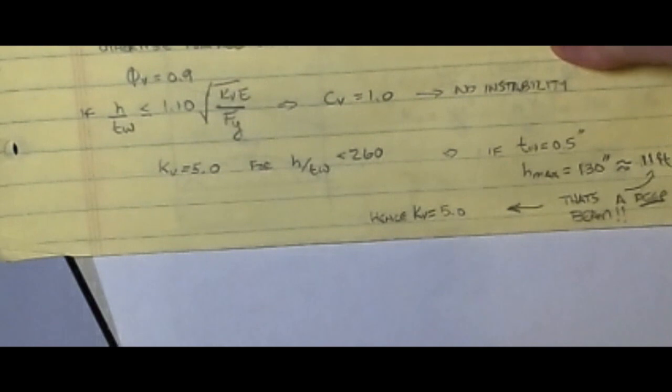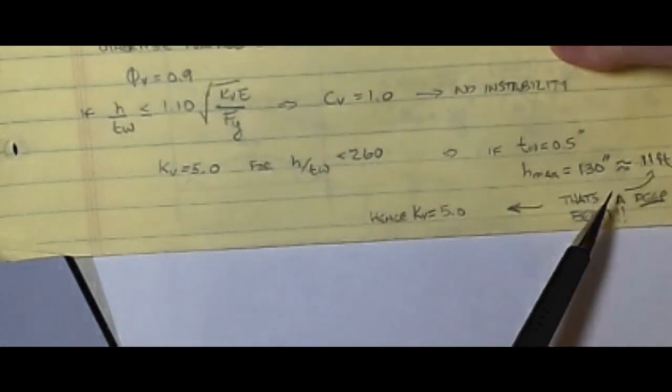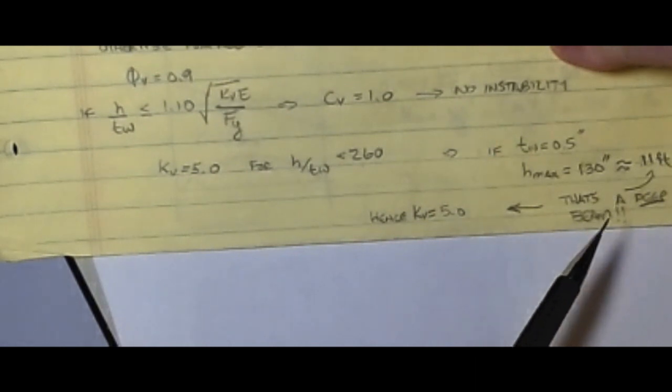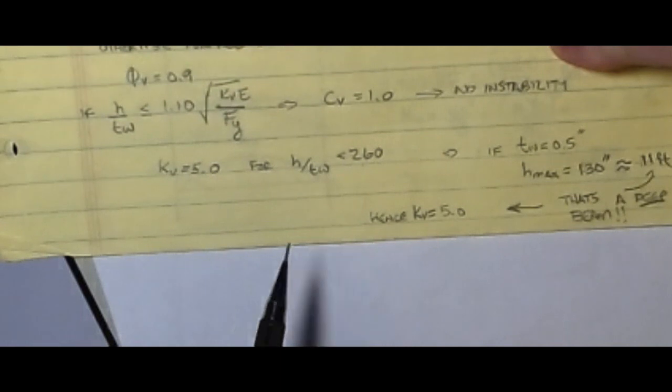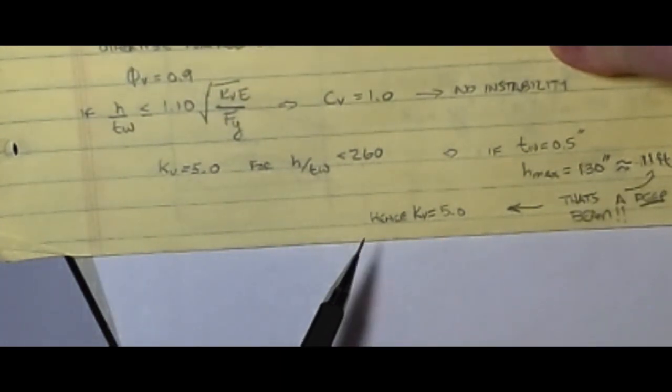Okay. I think the largest W section is a 44 incher or something. I mean, they're big, but they're nowhere near this limit. All right, that's why it's only a few cases, a handful, like 6 or 7 of them, that will violate this, that will have these shear problems start to creep in that we have to consider otherwise.